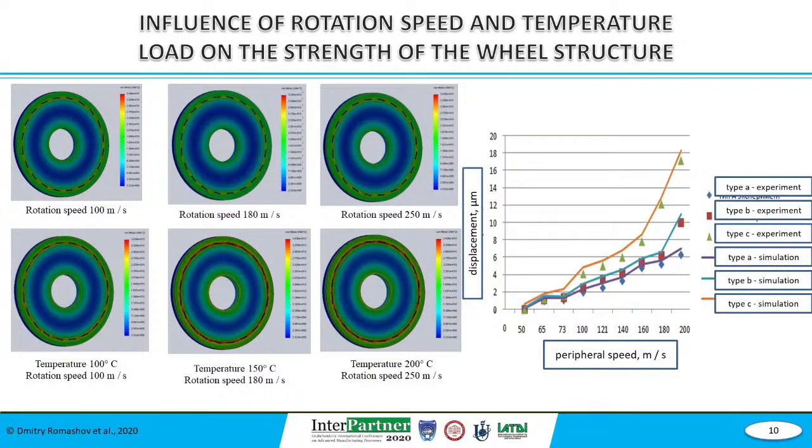Also, we are calculating and simulating the high-speed grinding process. So it's the same as the sintering. We have a mathematical model, we have the correlation with our experimental results, and we have the mathematical models which we can use when improving our expert system. Now these are the highlighted dependencies of stresses in the grinding area on the CTE, the coefficient of thermal expansion, of the metal plate during high-speed diamond grinding.